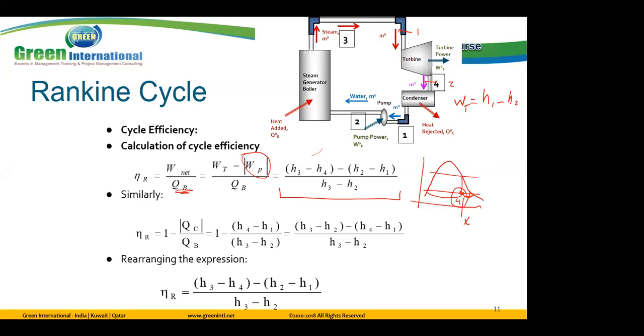We have here a source of external water, from a river or from the sea, going inside to cool the condenser so the steam becomes saturated liquid. So we don't pay anything for this, this water just gets heated and goes out. That's it. Okay, sir, thank you.